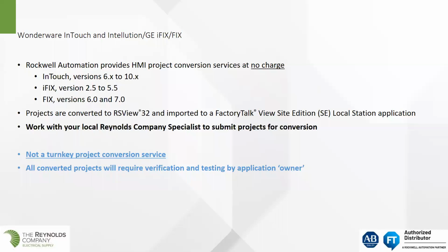And so it's important to understand that this conversion process that we're offering for Wonderware InTouch and also Invensys GE iFIX is really a step in a whole longer journey towards utilizing the Premier integration that's available with the Logix platform and FactoryTalk platforms. So when you're looking at doing PLC5 migrations and SLC migrations, make sure you include the HMI as part of that migration process. It'll definitely pay benefits later on.